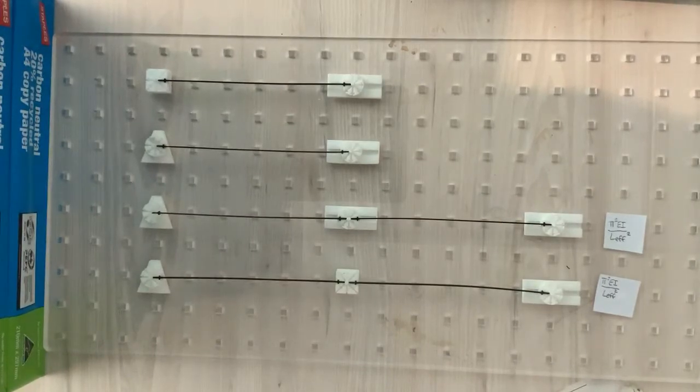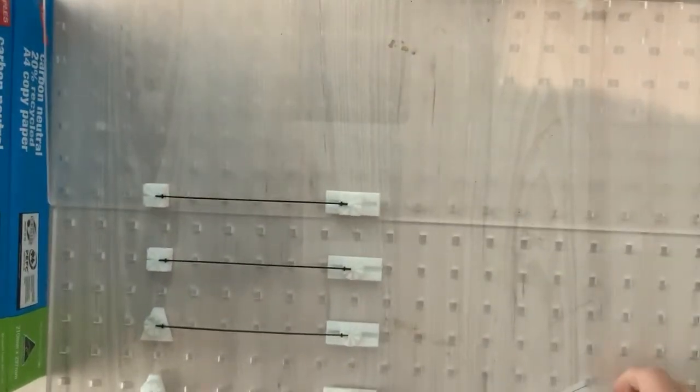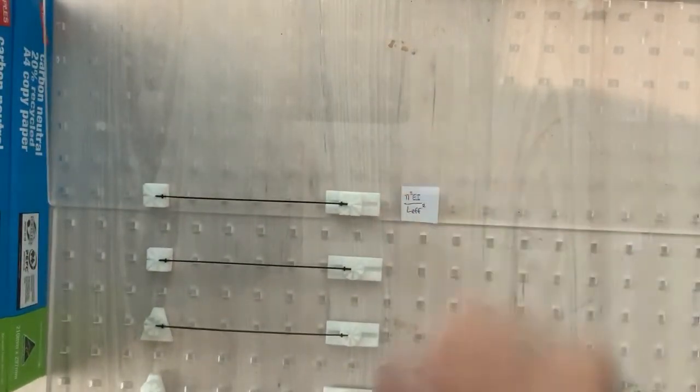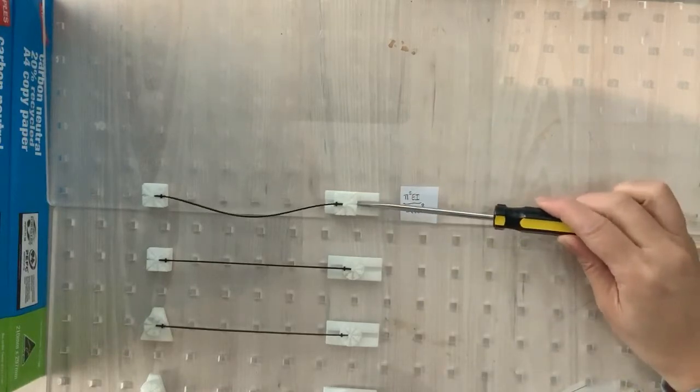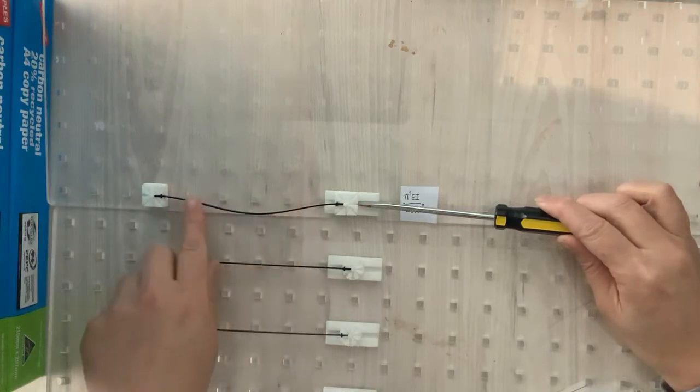And then from there, you will get the buckled load. And then in the last case that we talked about yesterday, you would say, what is the effective length of this one here? The effective length of this one here is going to be 0.5, half of 1 meter, half of this length.